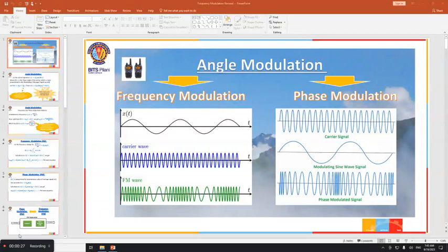What you are transmitting is a carrier wave, a high frequency carrier wave. So on the amplitude of the carrier wave, there is a message signal, right? Suppose that amplitude is corrupted due to noise, then you're gone, right? Your information is gone and it's very difficult to recover. Have you understood this? That is the reason amplitude modulation is not preferred.